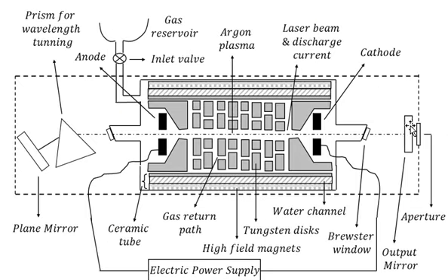So this is a fixed mirror over here, and this is the mechanism for the selection of the wavelengths. That is a fixed plane mirror and a plane mirror and a rotating prism structure. Both will be rotated together so that the mirror remains at an angle 90° to the beam which is received from the prism.